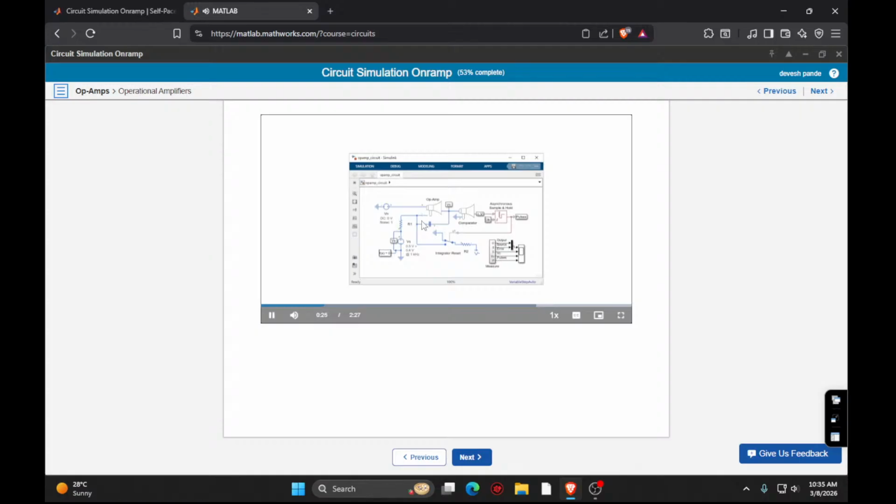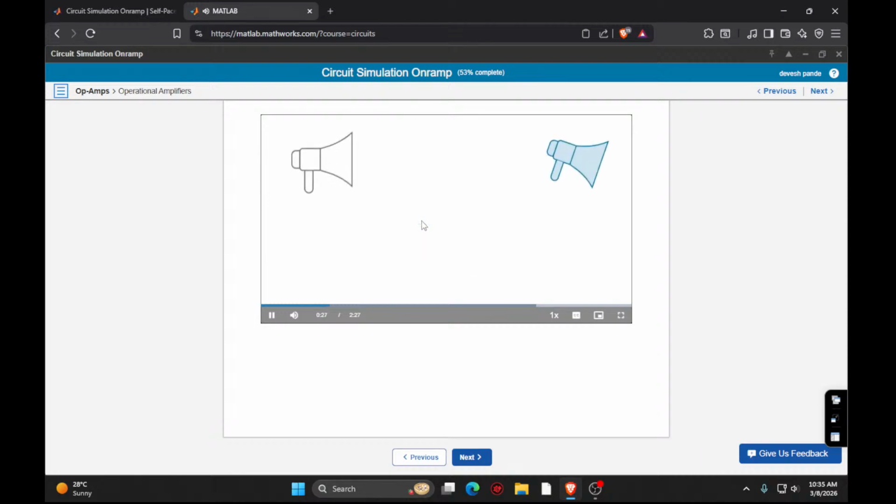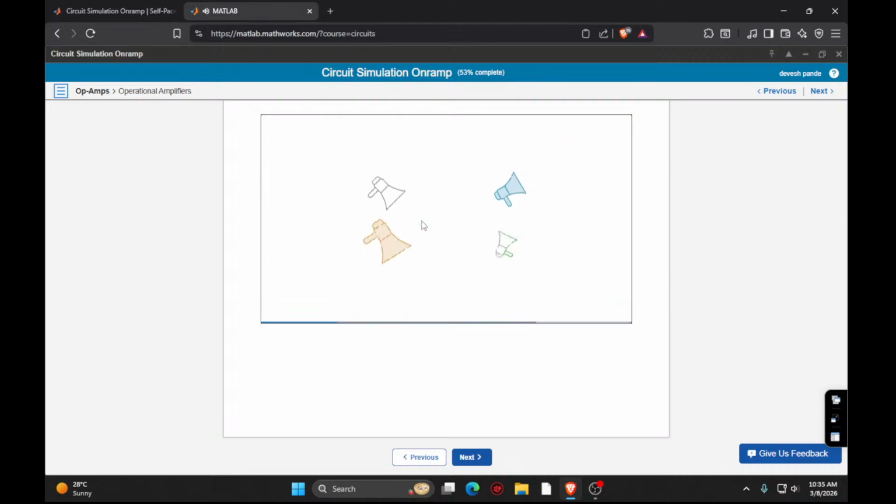Review some basic properties of op-amps. Op-amp chips can have many different architectures, but are represented using this symbol in a circuit diagram. The terminals on the left are the input terminals. The input voltage is the difference between the positive and negative terminals. On the right is the output, the amplified signal. In practice, op-amps are most commonly used in a negative feedback circuit. That is, a portion of the output is fed back to the negative terminal. This feedback stabilizes the op-amp's behavior.